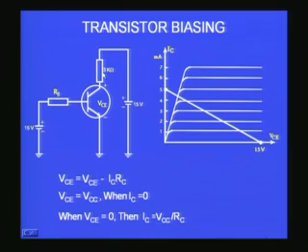This is the RC. So, in general, VCE in this type of circuit is equal to VCC minus IC RC, which is a very simple equation corresponding to Kirchhoff's voltage law. If you go along the loop, the algebraic sum of the total voltage should be 0. Therefore, the 15 volts should be dropped among these two devices. One is the resistor, the other is the transistor, and that is what this equation is about.